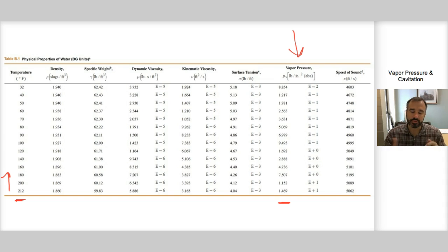So we always want to be very, very careful that we don't hit any cavitation level. In fact, this is probably the most important thing when we're talking about pump design. First, the pump has to be operational within our flow curves, but the second thing is cavitation. In a lot of cases, that's more important, because if you have an undersized pump, the system's just not going to work. If you have a pump that's going to cavitate, you're going to destroy the pump and have to buy a new one. So these are two trade-offs in design that we have to deal with.